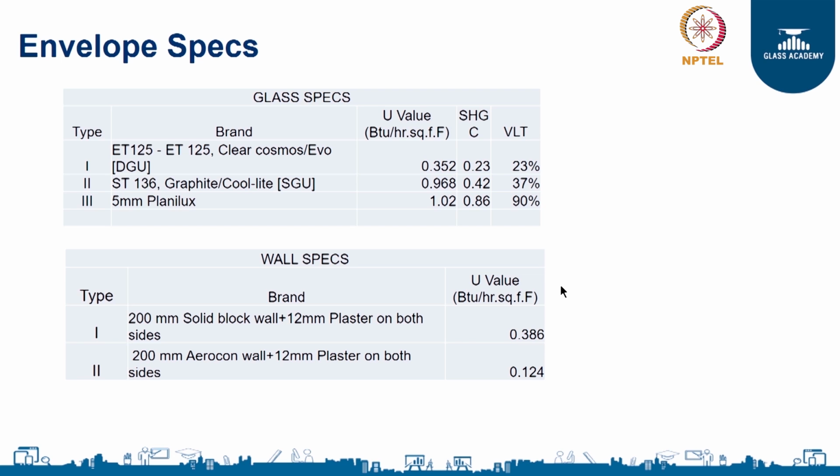So we try to see how you can still reduce one and try to maintain the level of daylighting depending on the sun path and so on. So you have a fairly good idea on combining the glass with the solar window and the solar path analysis, and see where optimally you can put this glass, which facade you can put, so that you get a fairly good idea on minimizing the SHGC. At the same time you get more daylight, right? So that's the philosophy.